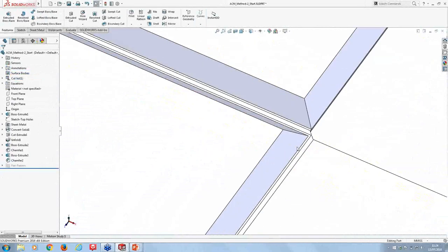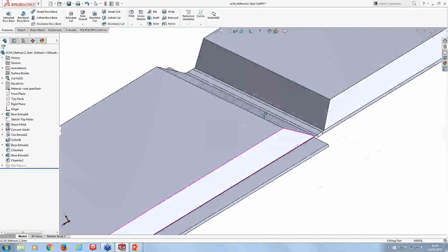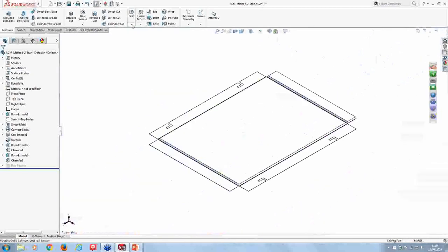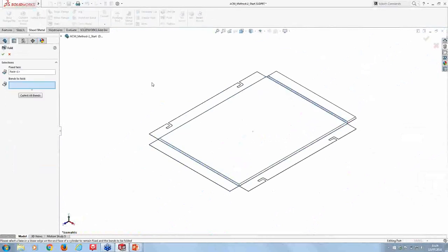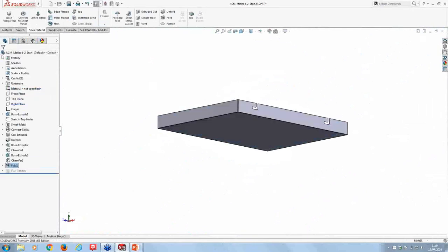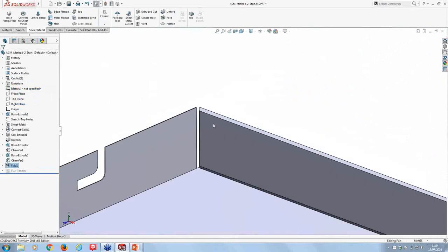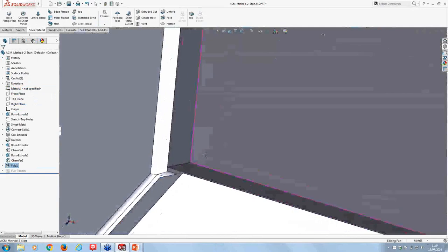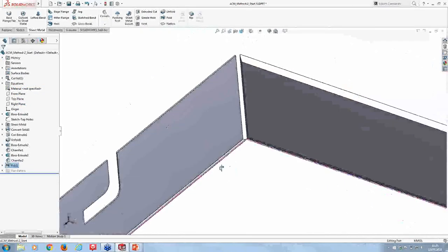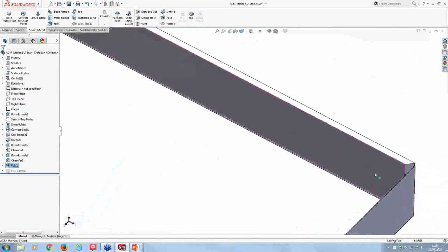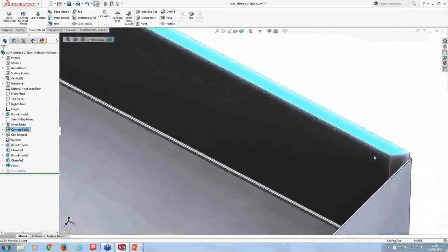Right, so this method here is assuming that we're using like a V-groove cutout. The advantage of that, if I come over to my sheet metal tools again and do a fold operation, collect all bends, you can see how it has folded it up using the sheet metal functionality this time. I haven't had to create two configurations manually here. Now, with this method, I guess the disadvantage is I'm not representing the three layers of material.